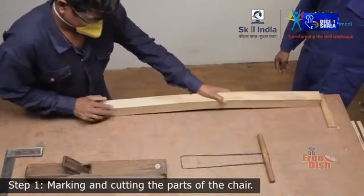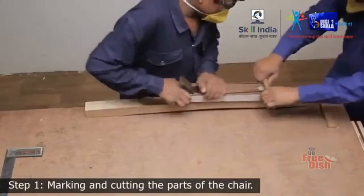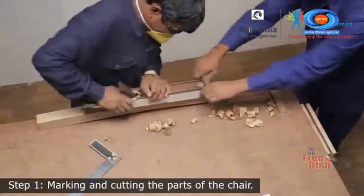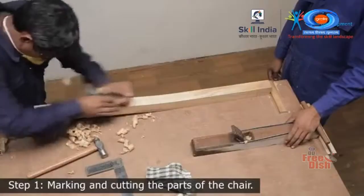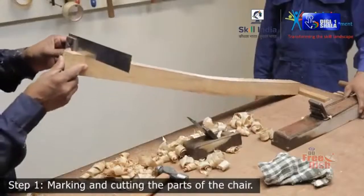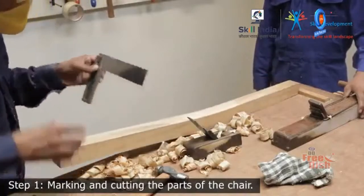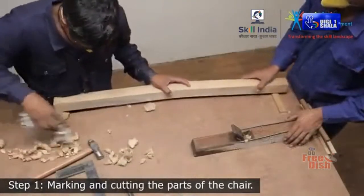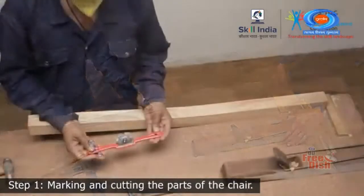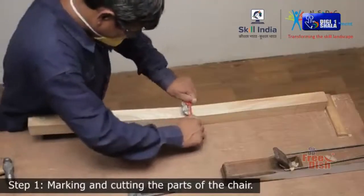Support the piece on the bench top and smoothen the surface with a bench plane or smoothing plane. Clean out the piece until it is smooth and flat. Ensure the squareness of the piece with a tri-square at regular intervals. Clean the work area of the wooden shavings left behind. Now, with a spokeshave, give the curvy shape to the bend on the center part of the back leg.